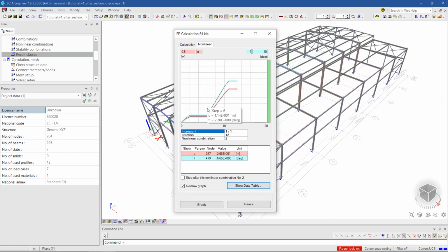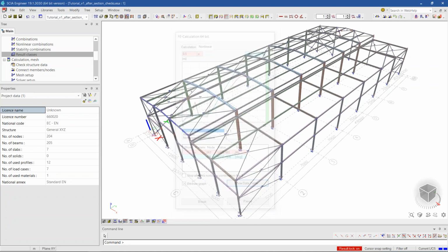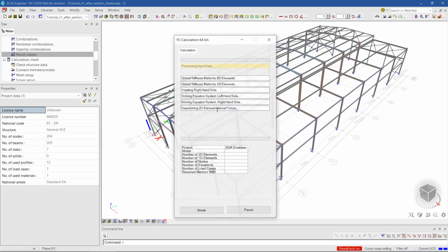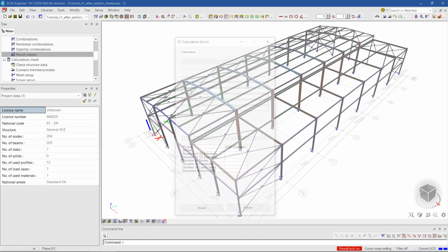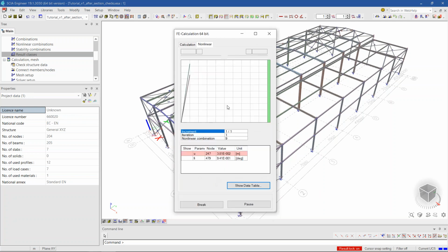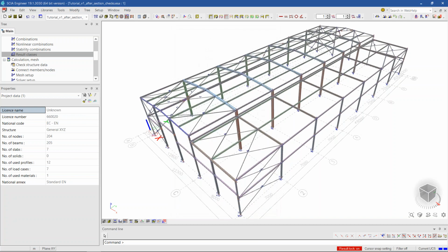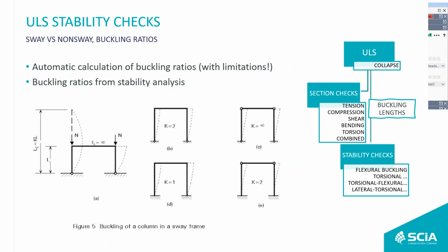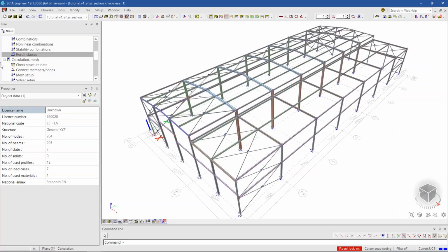And you can even see it here. There is not really a sophisticated Newton-Raphson analysis with stepwise application of the load. We have a portion of the load which is applied in the beginning, if you can see it here. And then the full load is applied on the rest of the structure that does not have compression diagonals, let's say. And so in fact, we still are running first order analysis. And this is why the calculation of these combinations doesn't really take so much time.